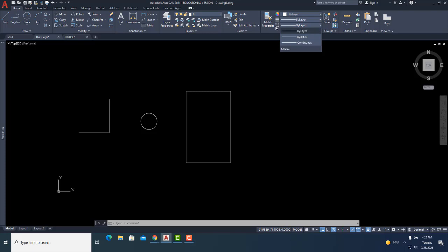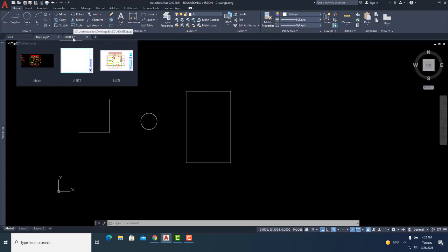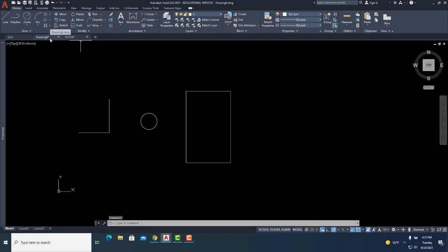And you can see right here, if you hover over that icon, like we talked about in week 1, you have tooltips, and that's for line types. Now, there are different line types that you're going to be using. Up to now, everything has been solid, but there are some line types that you might need. I'm just going to show you how to load them. Then when we discuss layers, I'm going to show you how to put them in the correct layer, and then how to make them show when you print. We're going to discuss that later on. For this one, it's just to load the different line types.